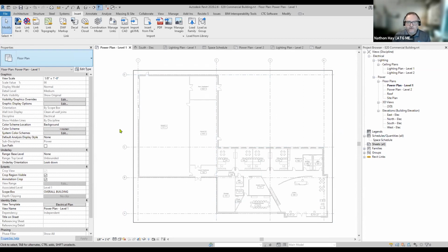Eventually in here, you'll have all your details. Like if you need to show your riser diagram, I'll show you that eventually, but it's basically drafting in Revit instead of AutoCAD. Revit just does not make a way for single line diagrams, but you'll get it and you'll get the box, just like in AutoCAD. You'll have blocks for your single line. You'll get them in Revit.